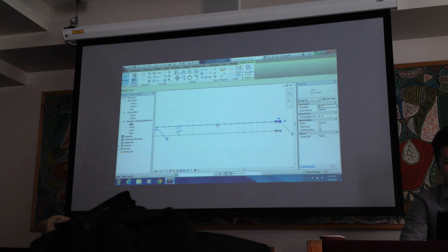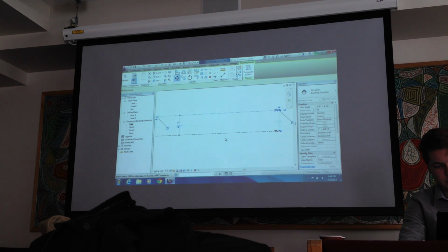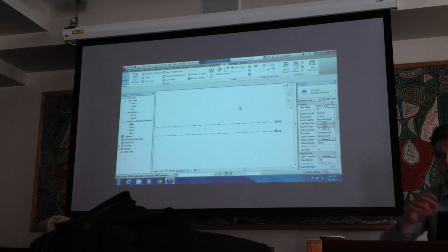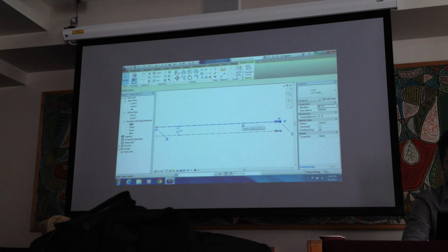Or you could type an actual unit onto it instead. So you click, and let's say you want 12 feet, you just type 12, press enter, and it'll automatically move it or copy it for you depending on what you want. How do you get the type box? Pardon? The type box. Where do you type? There's no type box, you can just type on your keyboard.